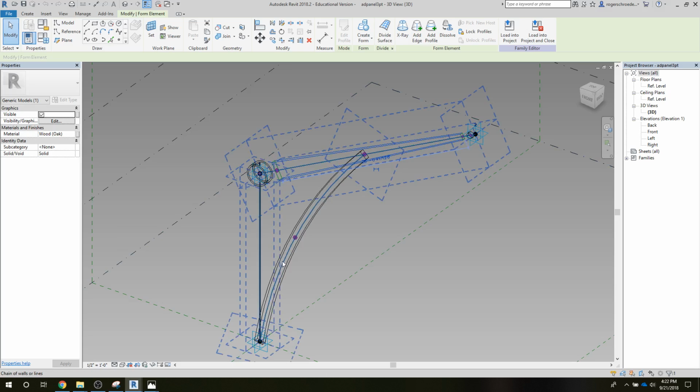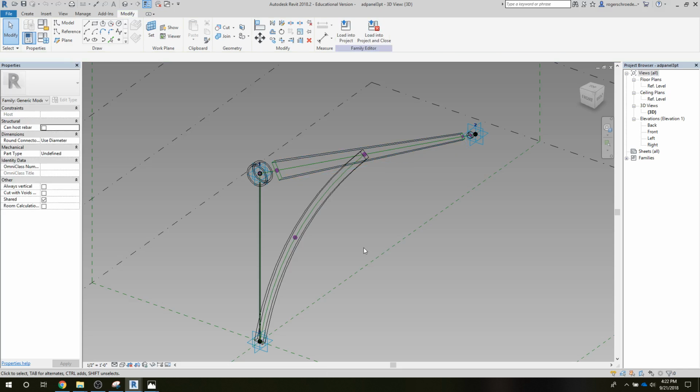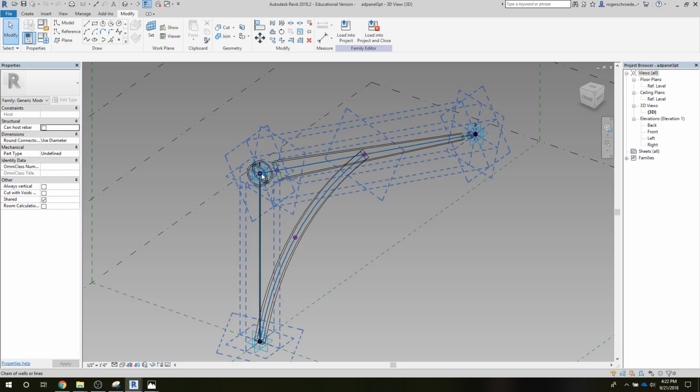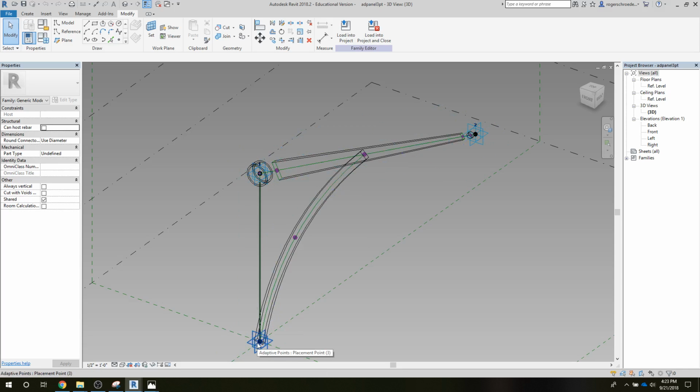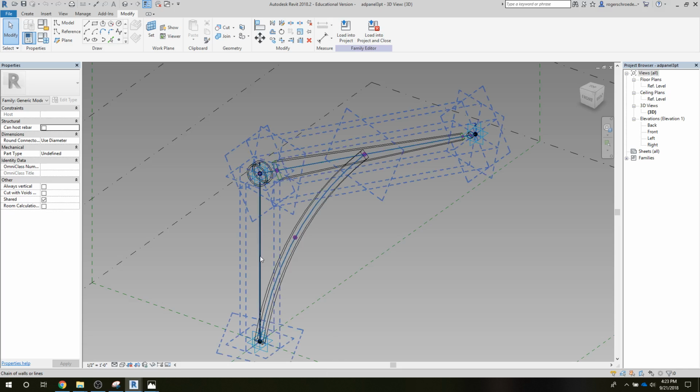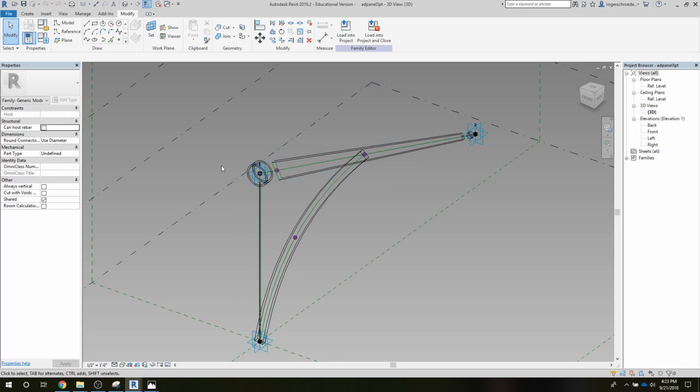I've defined a point on that reference line on both ends with two different size extrusions. This extrusion is on a NURBS curve where I've got a random curve point. It's not a good idea to have this kind of floating reference point because it isn't determined by any geometry, but it worked out pretty good for this example. And then I have a reference point between this point here and this point down here. I've extruded out a piece, what might be like a metal tension rod, just created an element up here.